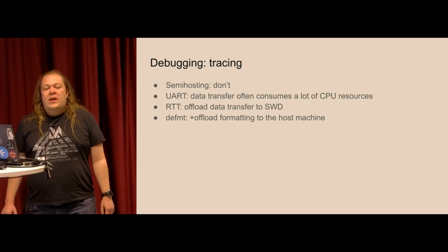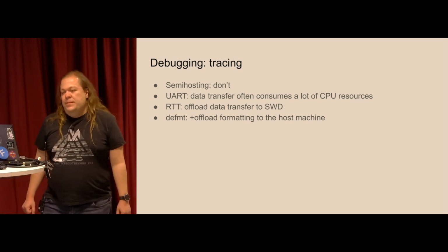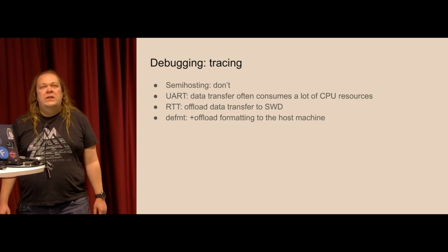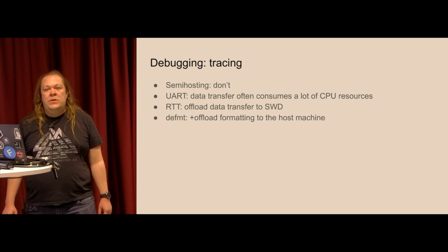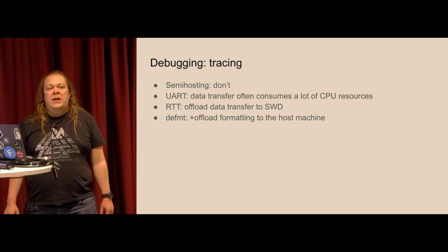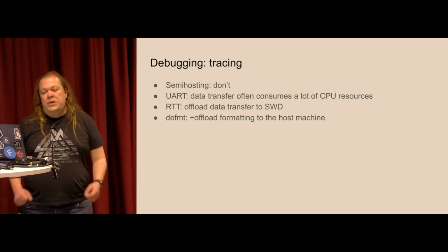Then we have UART, which is quite a simple approach. You just send some bytes to it. But UART is slow, but this is not the main problem because the amount of data may be not so big. The bigger problem is that sometimes you need to send a lot of data, but in small chunks. So you have spikes in required performance of your CPU.